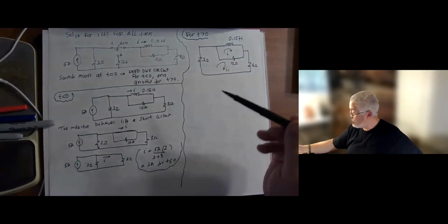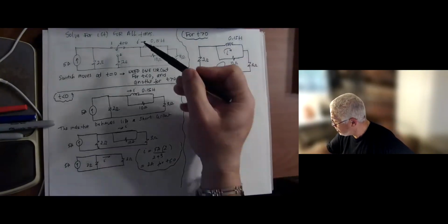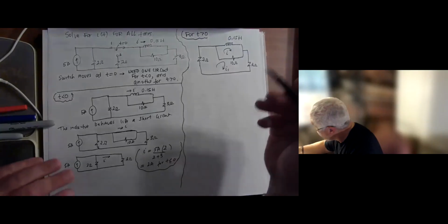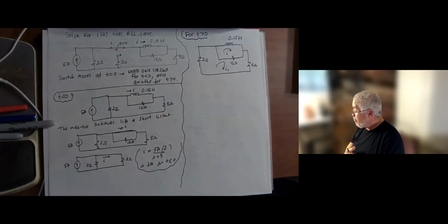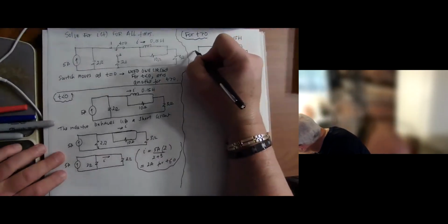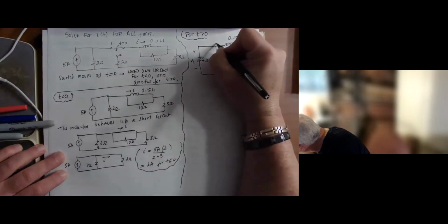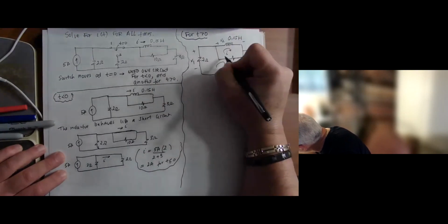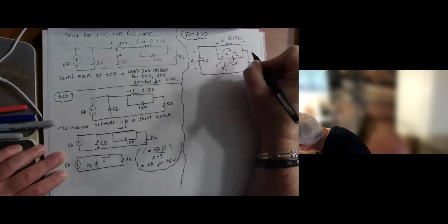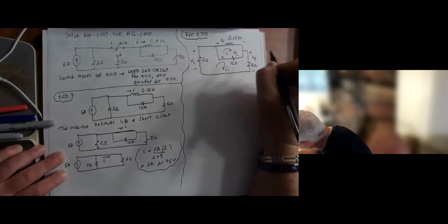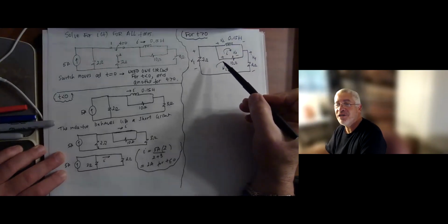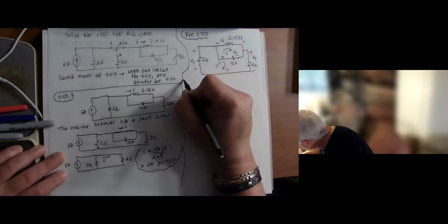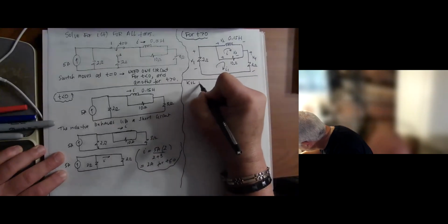I put my 2 mesh currents because I know the current through the inductor was the current I. Then I'm going to put voltage on my passive elements, just like I would carry on a regular mesh problem to come up with the differential equation here. So let's put V1, V2 across the inductor, V3, and V4 here. Okay, so 2 meshes, I'm going to write 2 KVL equations. So here are my steps. First step is KVL equations.